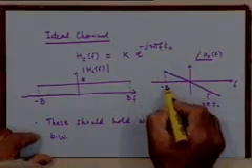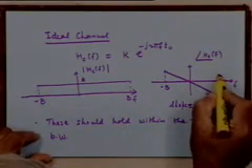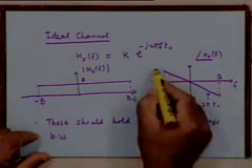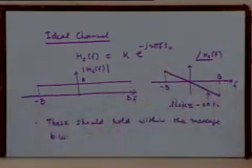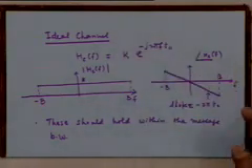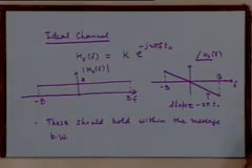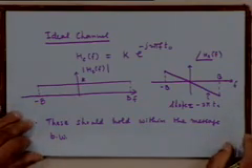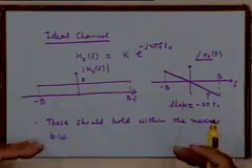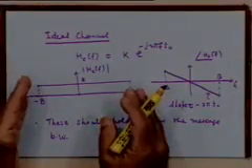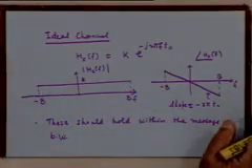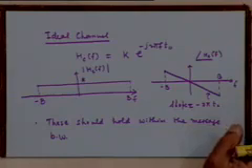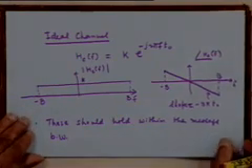Similarly, these linear phase characteristics should hold between minus b and plus b. After that, if it becomes slightly nonlinear or something else happens to it, it's not a straight line after this, it doesn't bother us very much, because the signal does not have any components in that frequency. Is that clear? So an ideal channel in a practical situation would be one which has these kinds of characteristics within the message bandwidth at least. Is that okay? Good. Any questions?